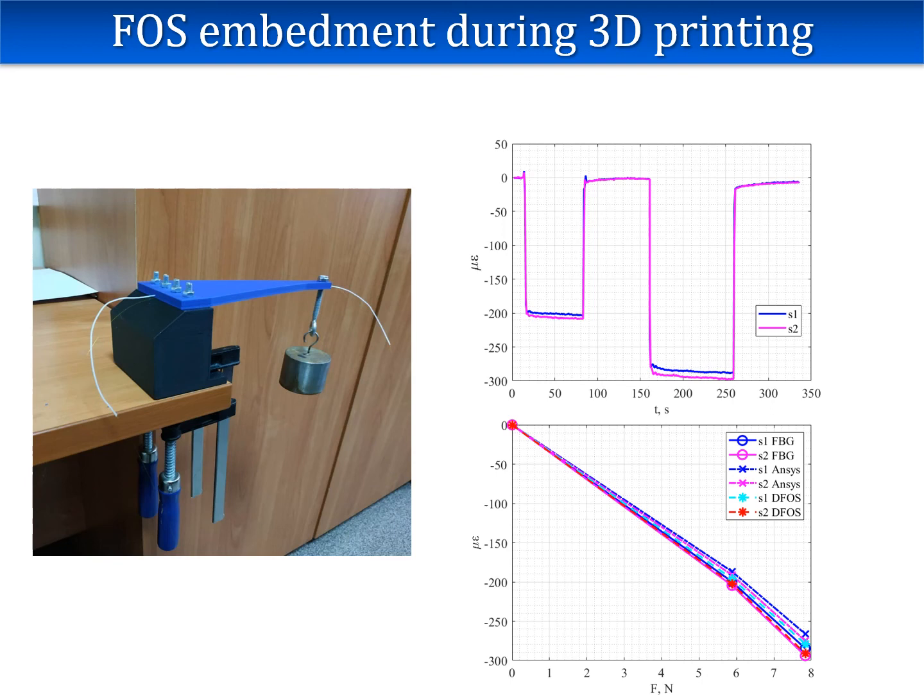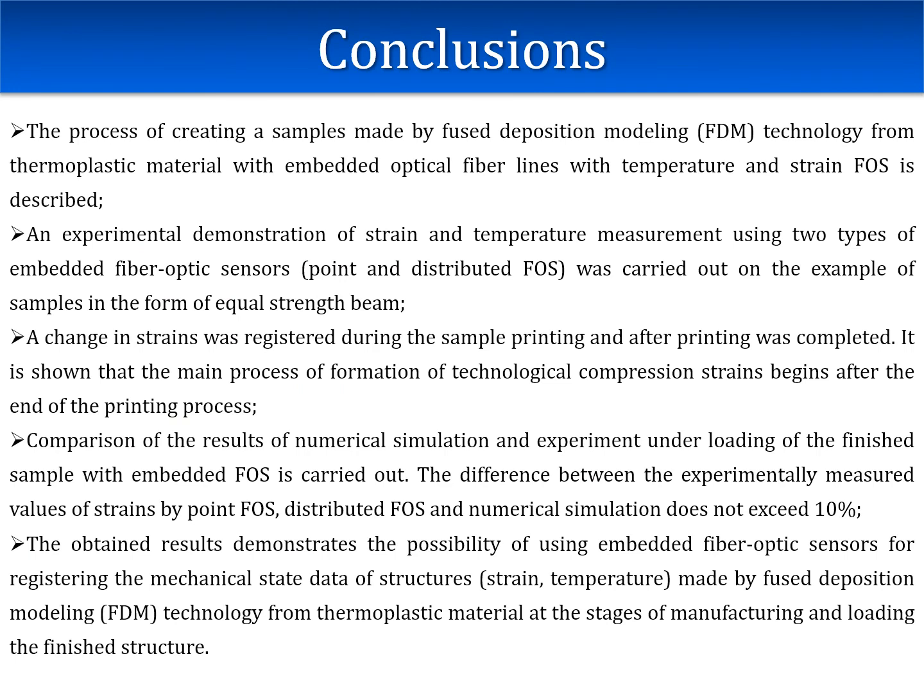The difference between the experimentally measured values of strain by the point sensor, the distributed sensor, and the numerical calculation by the finite element method and three-dimensional formulation of the problem of theory of elasticity does not exceed 10%. The process of creating samples made by fused deposition modeling technology from thermoplastic material with embedded optical fiber lines with temperature and strain sensors is described.